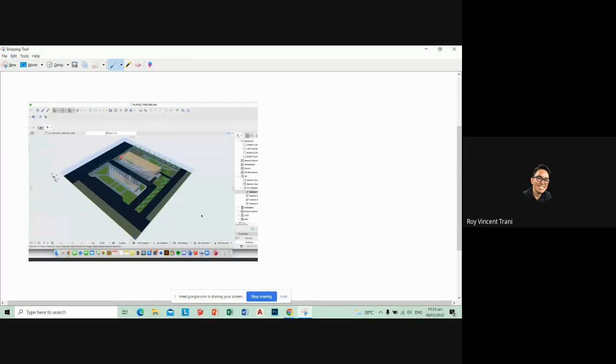I noticed you don't have roof eaves. You need to add roof eaves here, additional from the wall, maybe at least 1.2 meters. So the eaves of the roof should be 1.2, just to protect that.